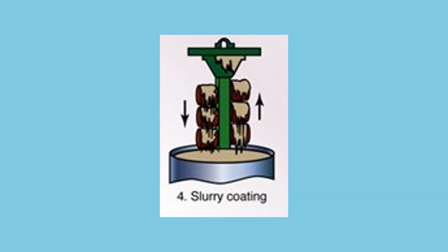The wax pattern and tree is then dipped into a slurry, and this slurry is a liquid ceramic or clay slurry, also known as refractory clay. As it is dipped into the slurry coating, it is often on an axle which will rotate it 360 degrees, and make sure that the whole wax piece is covered evenly. It will then lift the wax out of the slurry coating and be left to dry, and once it is dry, it will go back into the slurry coating to give it another layer. This happens multiple times until the correct thickness is achieved.